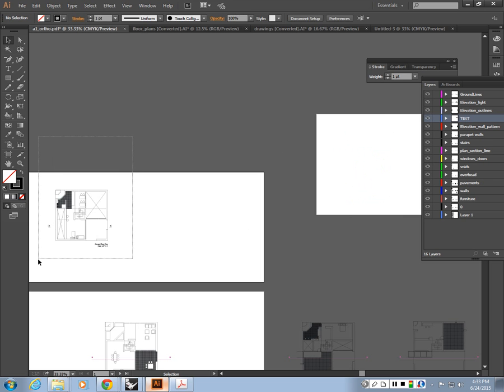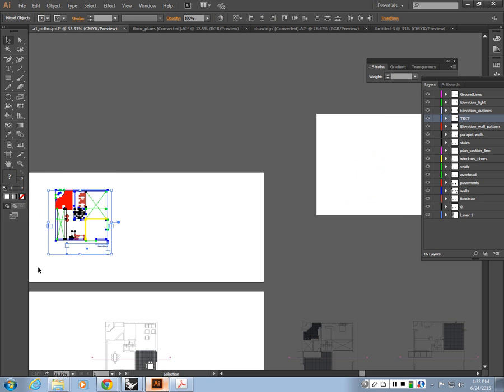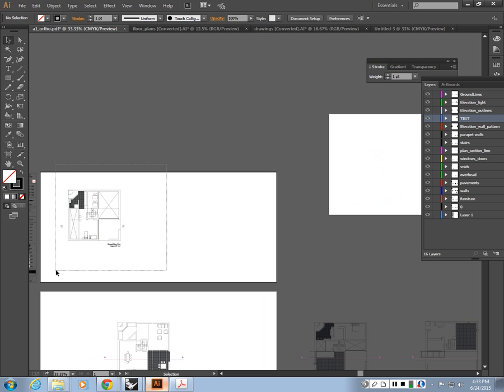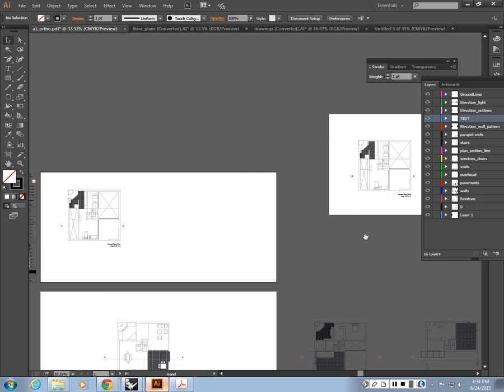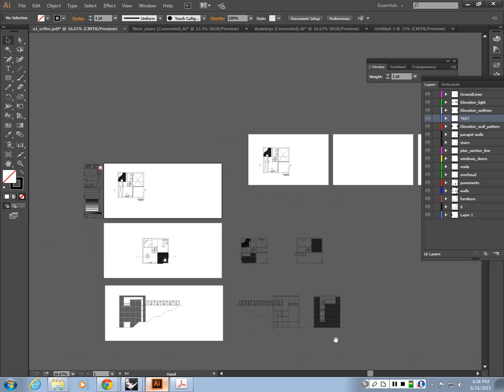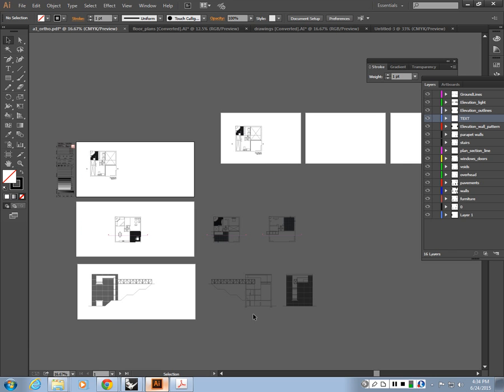Well, I basically selected everything of the drawing, and then went over to one of the geometries that belong to that selection, and then hit Alt, and while holding the Alt key, I'm dragging it to make a copy. And I can do this for any other type of drawing I want to print. So I can print one section, one elevation, one plan.